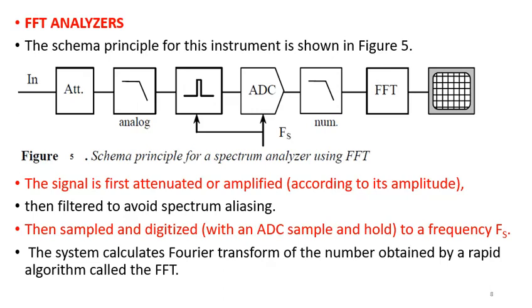in your analog signal. So now, if you don't use a filter, you may encounter a problem, because if the fundamental frequency of the signal, let's say, is 10 kilohertz, and you don't know that harmonics exist, the harmonics are multiples of that fundamental frequency. Maybe let's say the second harmonic, that is 2 times the fundamental frequency. Let's say it is 20, but we know the original signal is supposed to have only 10 kilohertz.